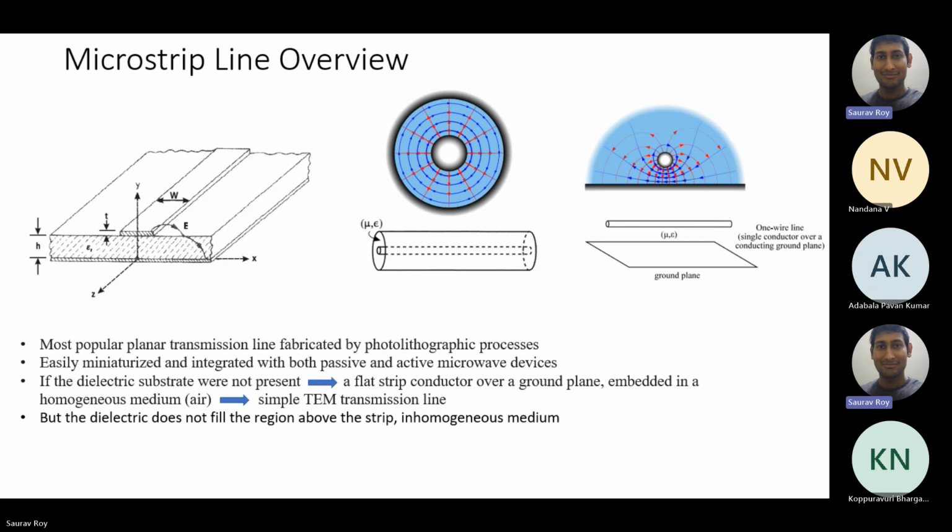Okay. So now, in the coaxial line, we have almost like a TEM transmission line. Similar TEM mode we also discuss in microstrip line. Because all of them are now connected like this, in the two-wire line or coaxial line, we have TEM modes. So that similar mode, generally called quasi-TEM, not exactly TEM, but it is kind of like TEM mode. So it all comes into the picture like this because they are all equivalent to a coaxial kind of transmission line.